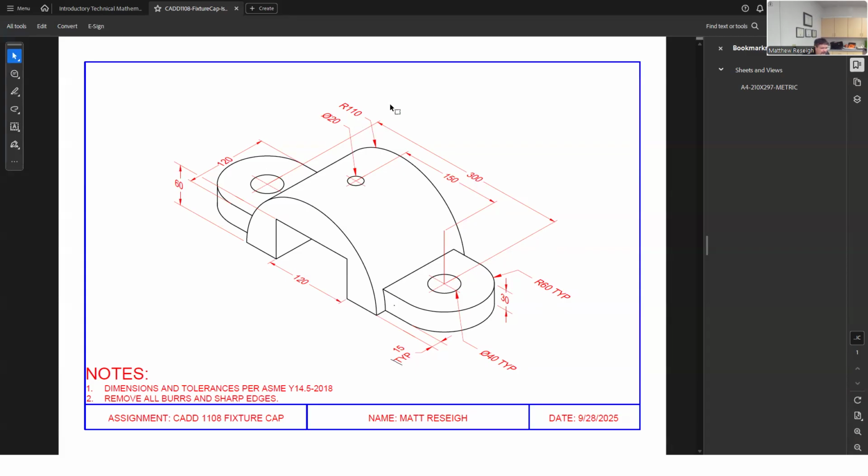And then the top view is going to have the same width, the 420, but it's going to now have the depth associated with it. And so the depth of this, I hope, is kind of given. The ear itself is 120, and then it's 15 on each side of the ear. That's typical, meaning all the way around. I likely won't use this kind of dimensioning, these typical dimensions. I'll use the dimensions, but I won't use the typical callout. So that's another 30 plus that. So 150 is going to be the depth of that.